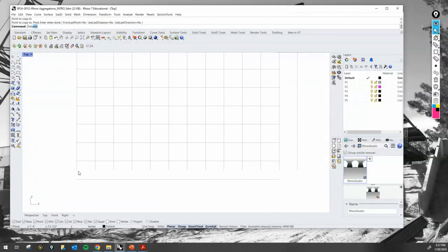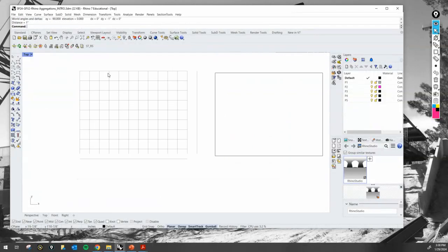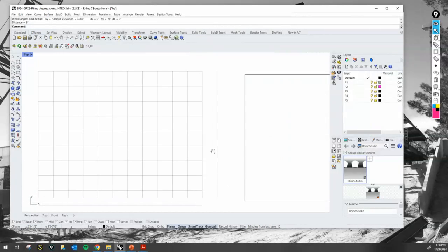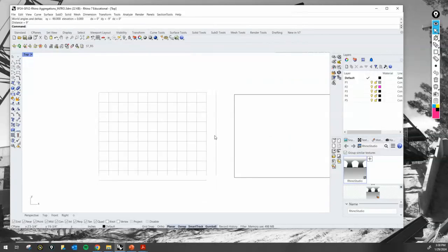And it's very important that you double check this distance is accurate. That's 1 inch, correct? And from there to that perpendicular, it's 9 inches, okay? This is a good opportunity for us to remember how to use the extend command.